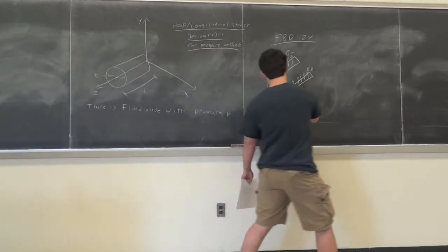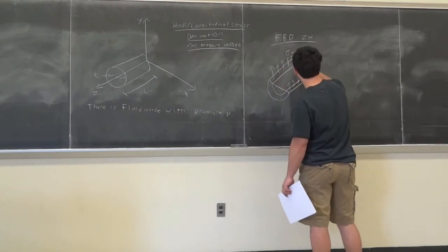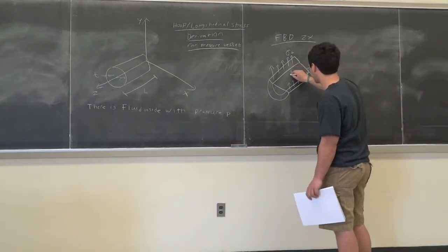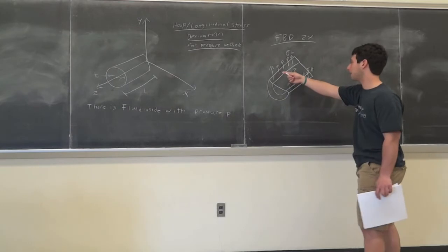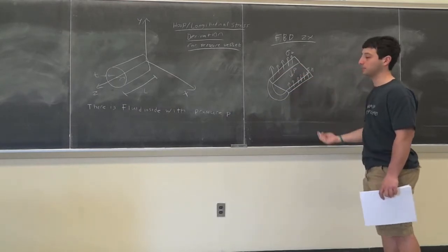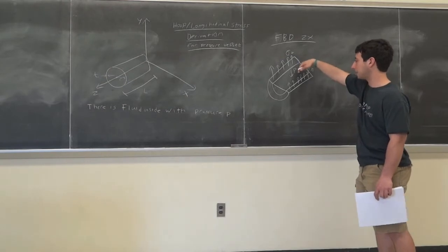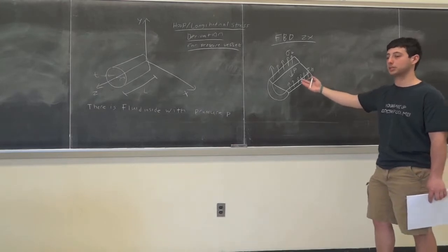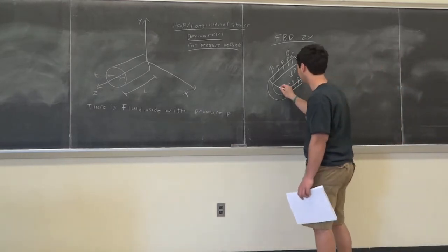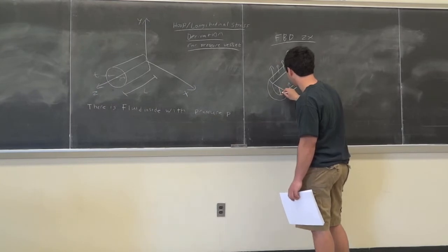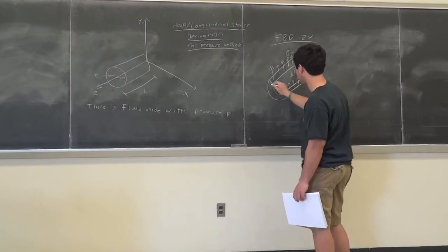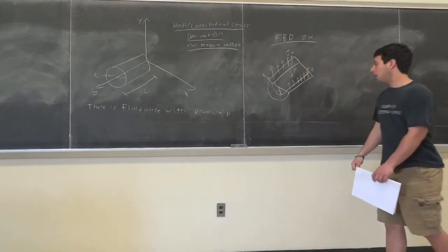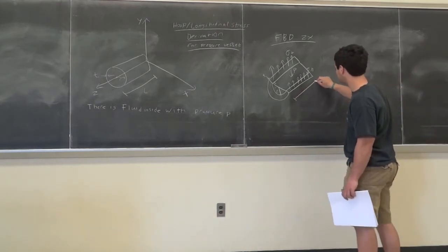Okay, so there's going to be a pressure facing downwards. So there's a pressure acting downwards. So I'll call this P, and then you have hoop stress along the wall thickness over here, pointing up in the y direction. This is in the negative y direction, P. Okay, so these are the only forces, right? They're stresses, but they're forces because they act over an area. So they give you the inner radius R, and they give you the wall thickness. This wall thickness over here is T. Okay, and this length over here is L.